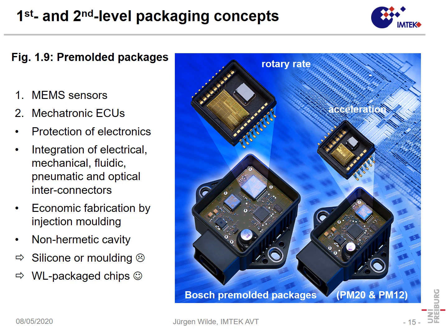As we can see, it's so-called surface micromachining structure, and here we have some movable interdigital electrodes, and these change the capacitance of the device, and from the capacitance we can see, for instance, if there is a force on that device. That means, do we have an acceleration or deceleration or some rotary rate which leads to centrifugal forces.